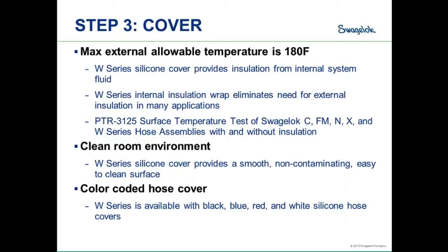Now, as far as the cover goes, in an insulated type design, again, 180 degrees F. Well, it has a silicone cover, and then it has an insulating wrap inside, so that looks like it's going to hit the mark. And then we see that there's a product test report. So the PTR is product test report. So a test was run to put media through this hose and then measure the insulating characteristics of it. So we now have a proof source.